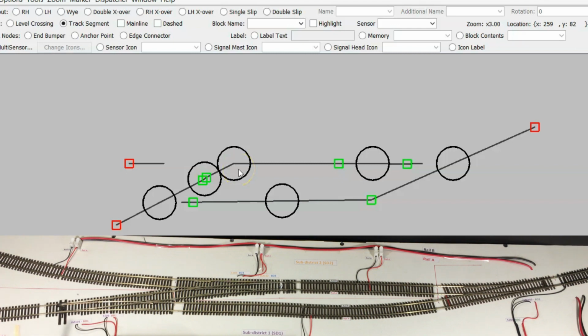So now, just like how throwing 101 affects 102, let's see if throwing 102 affects 101 as well. So let's go ahead and throw that. So exactly, there you go. So now, anytime you want to pass a train through this crossover or in their independent routes, all you have to do is click either of the turnouts, and both the turnouts are interlocked, and the basic safety measure for the crossover is already in place. How cool is that? Right.